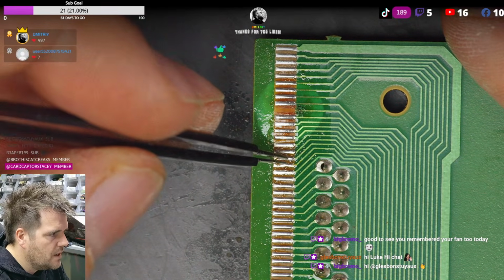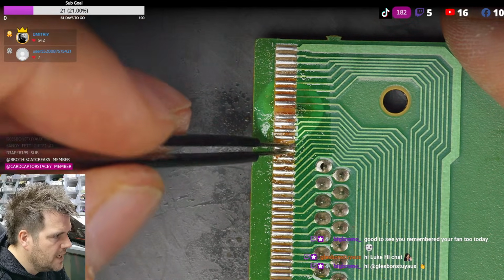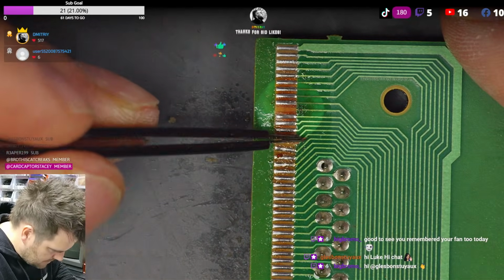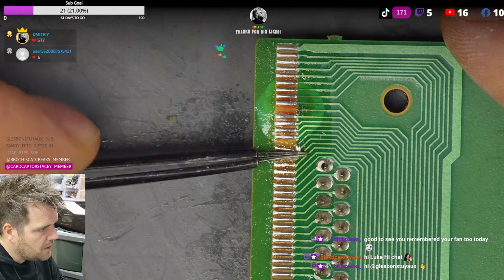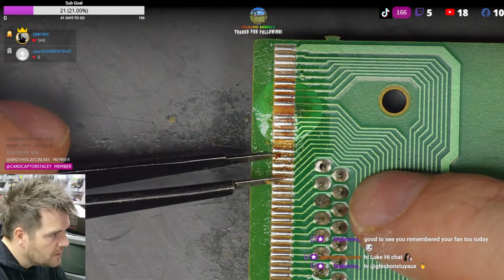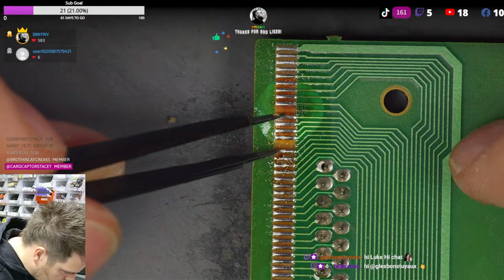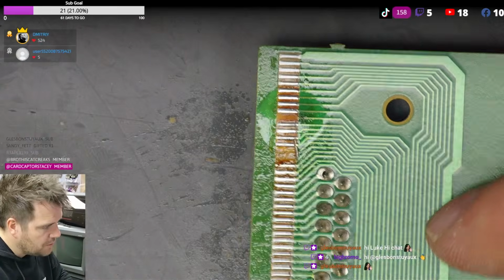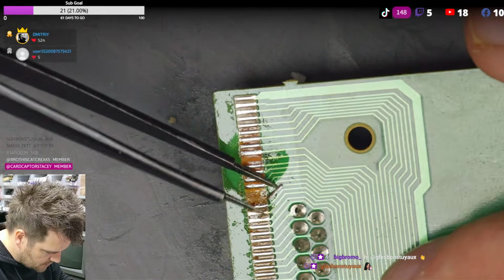They're very weak. I might just snap them off because they're moving, and then we'll solder wires. Yeah, I'm going to snap those two off because the fact they're already moving, they might be strong, but I don't want to risk that. I'm going to wiggle them off, and when we put the connector down, we're going to make them onto the traces. I don't want potential weak connections looking like they're good, but they're actually weak. So let's finish the job and terminate these.